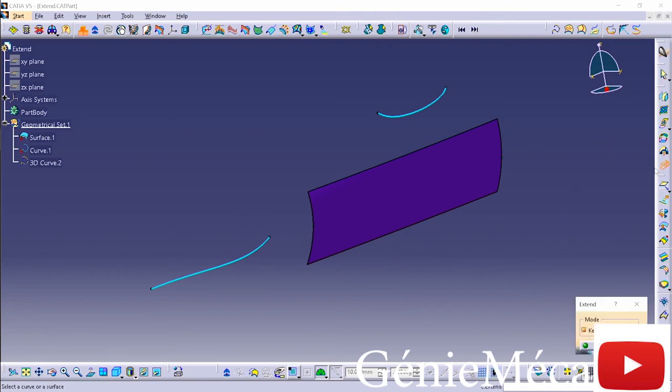I can do the same thing with curves. Now notice that this curve has no history. This is a NURBS curve that doesn't remember its parameterization. It knows that it has control points. It knows that it was constructed. It knows it has all that math, but it doesn't have the parameters of the points that initially were used to create it. So when I modify this curve, it allows it to modify simply without any issue.